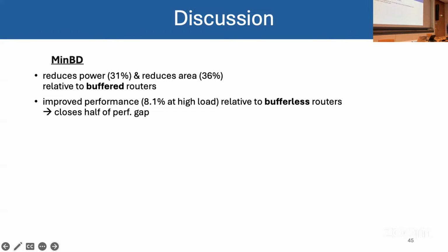Yeah. That's actually about wormhole switching in general. We don't keep the information at the body. In the router, we keep the information based on the input port that the head enters. So the header needs to enter some of these routing steps. In general, in wormhole switching, we need to do the routing algorithm and channel allocation, for example, for the head.